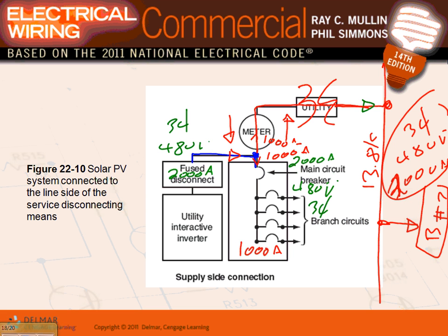You have to mark the disconnect, guys. This is where your inverter has to isolate yourself from the grid if the grid is down, because then now you're feeding the grid with power, and you could kill electricians or burn your system. It will trip, but you don't want to feed back into the grid if the grid is down.